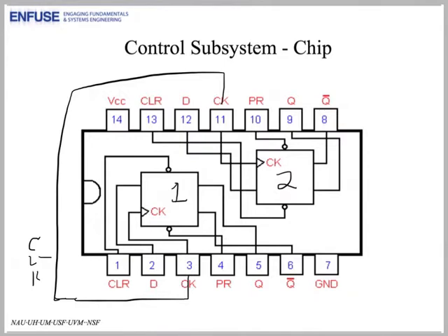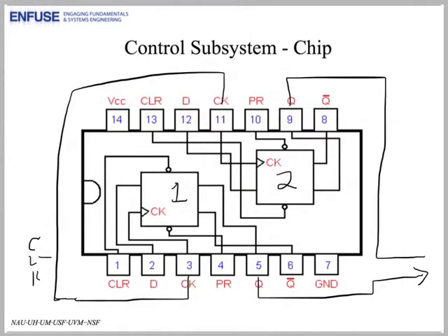Now there are two output signals from our control system, which is on this chip. The control signals Q1 and Q2. And both of these go to the H-bridge. And they are actually routed to MOSFET gates of the H-bridge.